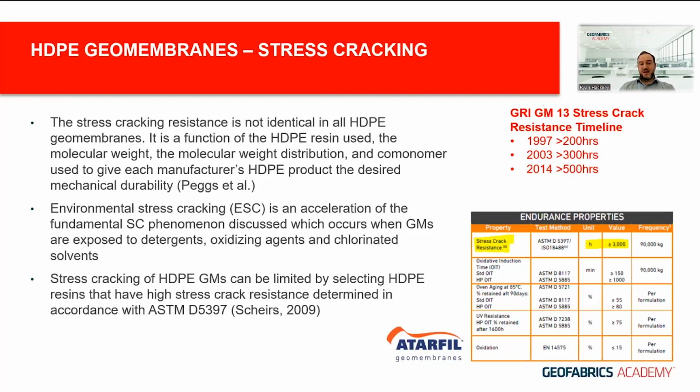And stress cracking can be limited in HDPE by selecting resins that have high stress crack resistance, and that's determined in accordance with an ASTM test method, ASTM D5397, and we have geomembranes on the market that can achieve in excess of 3,000, even 5,000 hours now.